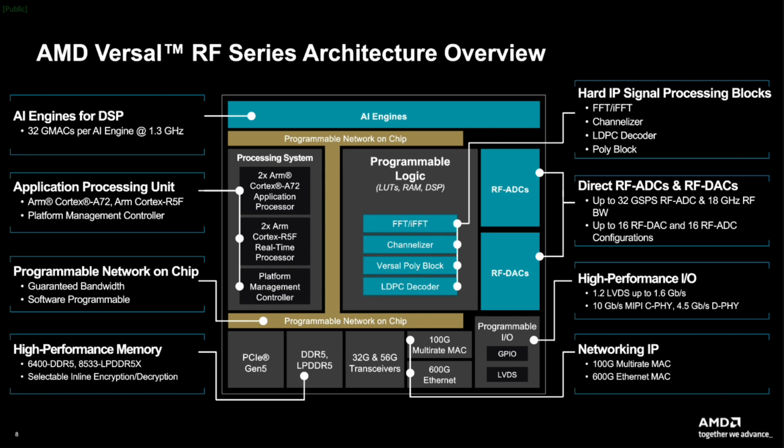But probably the most significant difference between the Zynq UltraScale Plus and the Versal is the addition of what we call AI engines, for adaptable intelligent engines. They are really a vector processor. And when you look at this upper area here, it's a two-dimensional array of vector processors. And this particular one is actually the original one that we used on the BC1902, and it's really a vector processor that's optimized for signal processing.